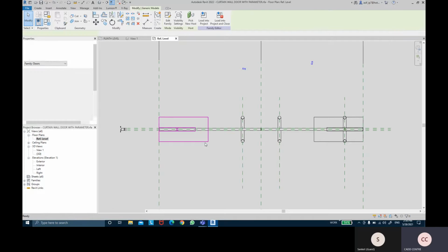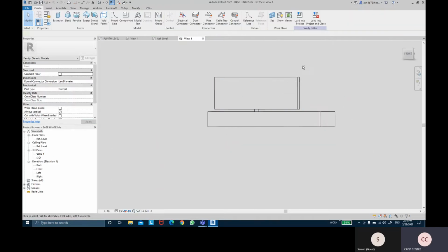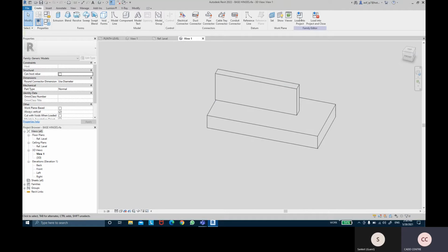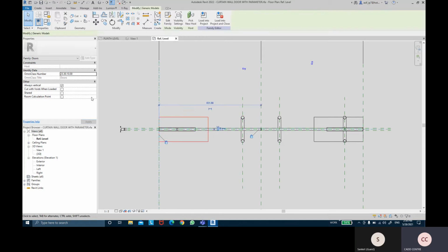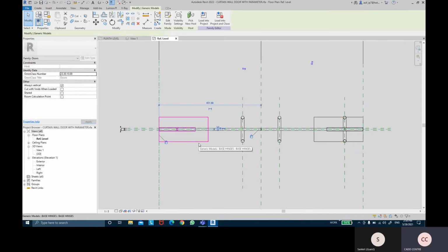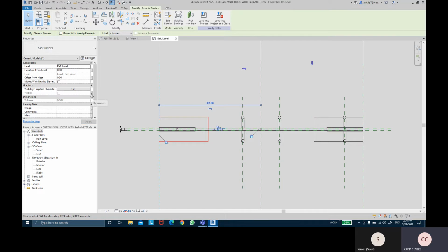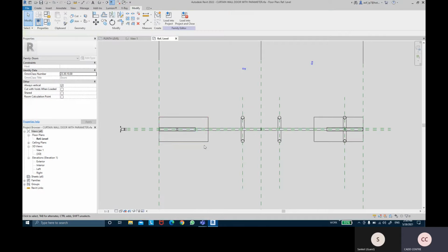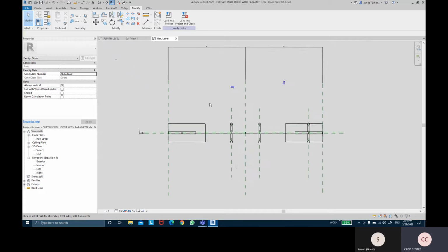Okay, so this is that hinge actually, and we have already provided everything to this parameter, so I'm okay with that. Just want to make sure that we have the visibility parameter. Yes, it has. It goes in the single panel, and this one goes in the double panel. Give this visibility parameter a name as well, like left and right. Okay. We'll deal with that later on then.